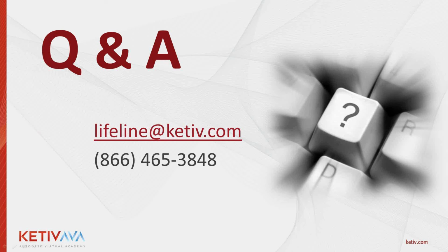Another question comes from Jeffrey. Can iLogic be used to drive documentation or drawings? iLogic is built on Visual Basic, and with Visual Basic, if you have some type of document, let's say in Word or Excel, then absolutely you can use Visual Basic to drive that, and you can put Visual Basic code inside of iLogic. There are also additional tools that I didn't review today. There's a tool called Configurator 360 that, if you're interested, we can give you more details on. It has some out-of-the-box tools that let you set up templates in Word, and it will automatically use the CAD models to generate quotes for you. So we do have some options there, even though I didn't review that today.